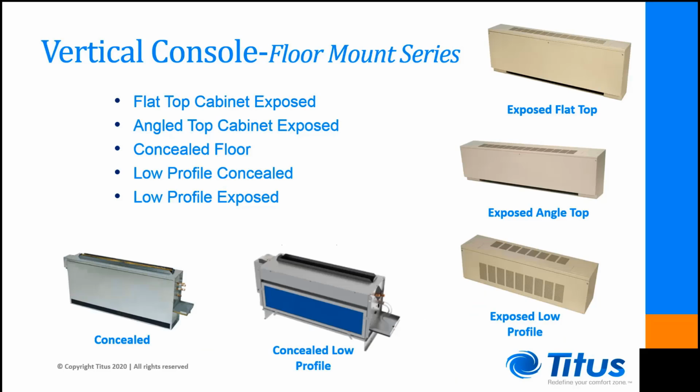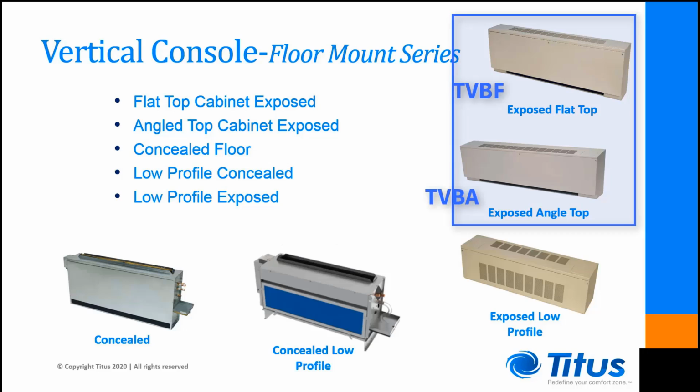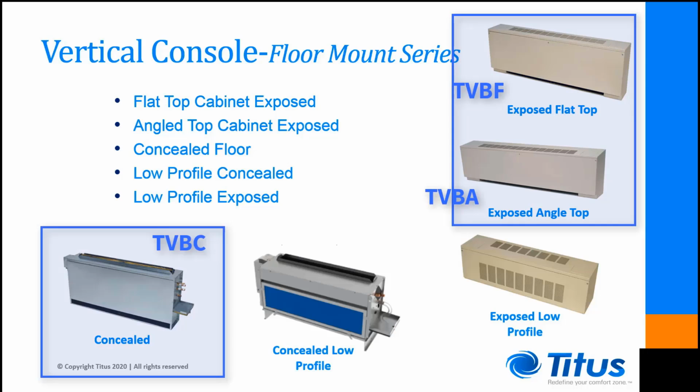Here we can see the next major family with its two subcategories. These are the fan coil units that we refer to as console units. They sit on the floor, up against or behind a wall, and are oftentimes found under a window. The two units in the top right corner and one in the bottom left corner of the slide are full height units at 28.75 inches for the TVBA unit, 25.25 inches for the TVBF, and 25 inches for the TVBC unit.